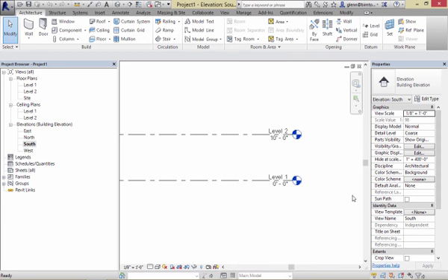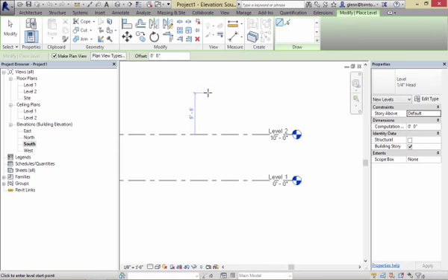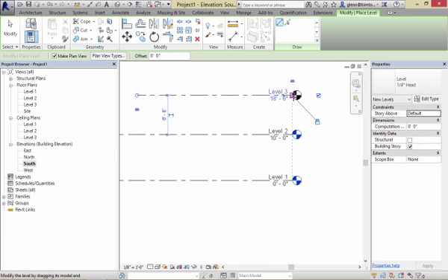So, in that elevation view, I'm going to go over to the level tool. Okay, levels, actually, on the architecture tab, it's over in the data section. It lets you draw additional levels. So this is where all these levels come from. If I want to draw another level, I can pull on out. Okay, and there's level 3.